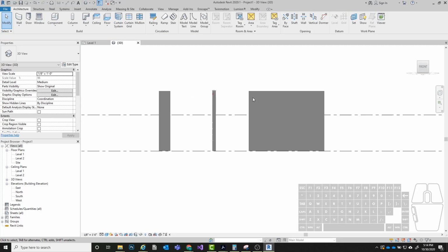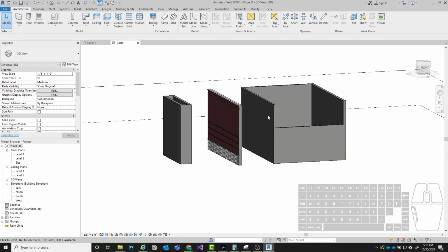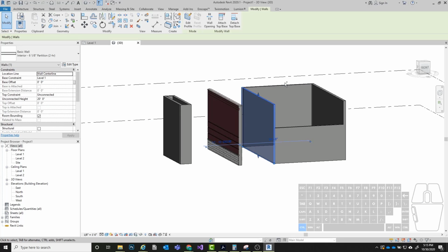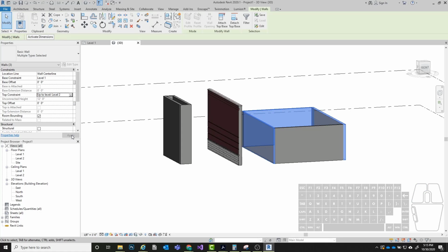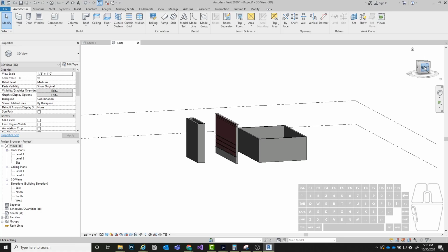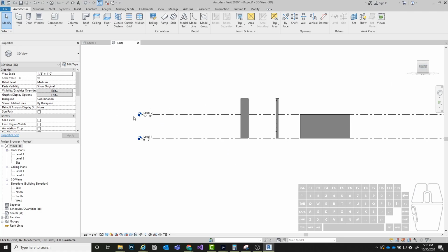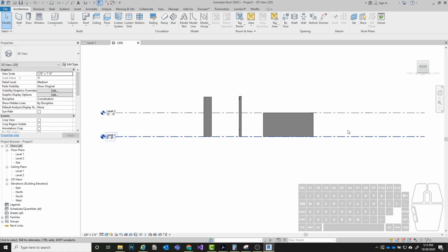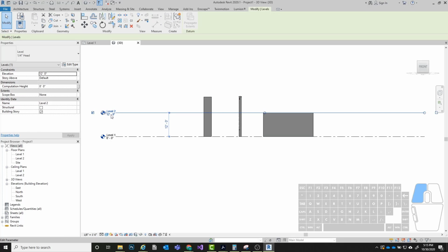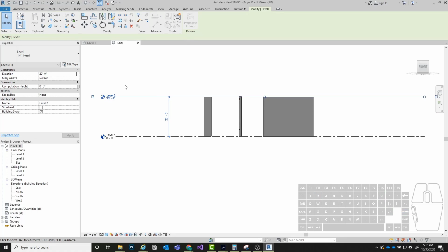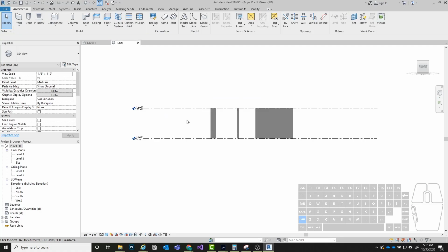All right. Let's say I want to tie the rest of these walls to that same level as well. All I have to do is click on all these walls. So click that one and then hold control to click my other two. And when they're all selected, go over here in the menu, switch my top constraint to be up to level 2, and then click apply. Okay. So going back to my front view now, you can see my levels are correctly tied to my wall right here. And if I go in and change that level height again to be like, let's say 20 feet, hit enter, the level moves up and the walls go with it. Okay.